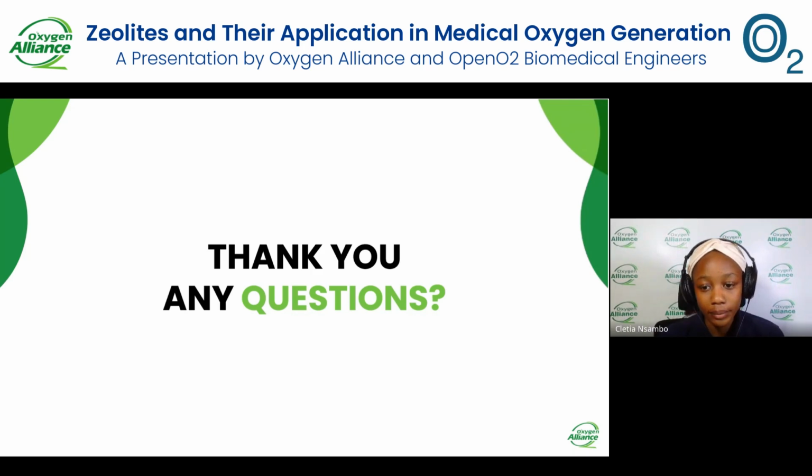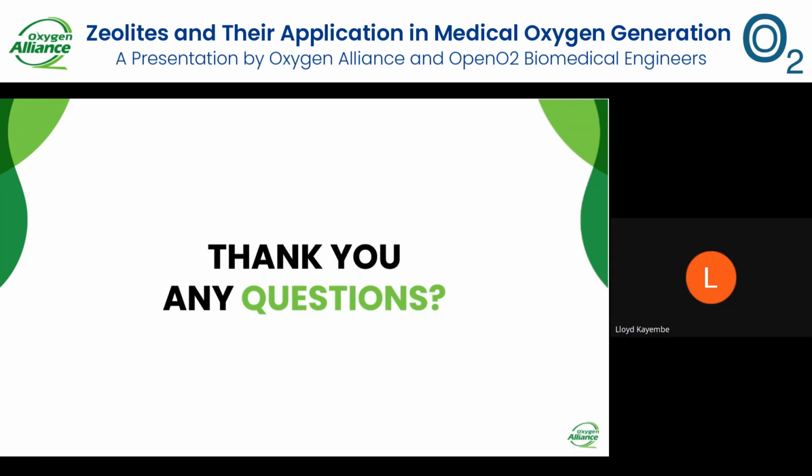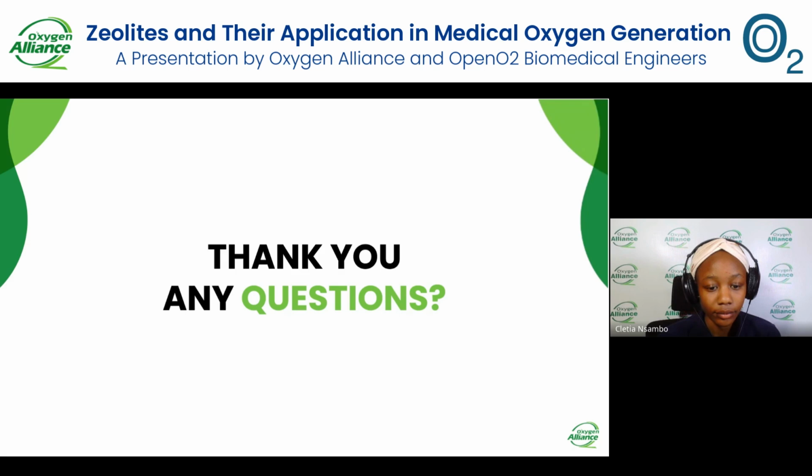Lloyd, I saw a hand. Yeah, I just wanted to add on to what Chimweme was saying. It's just better to take measures to avoid exposure of the zeolite to the environment. So whenever you are opening up the zeolite canisters, make sure that you observe all the measures to avoid exposure to moisture. I hope that has answered your question or added more clarity.